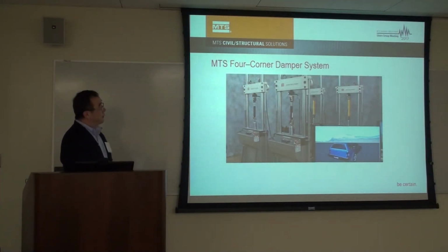So another trend we see is hybrid simulation being used in other industries like the auto industry. We have a car here, and the damper is a really nonlinear component, it is active, and it is coupled with the computer. So it's really tough to test those dampers. So we have a car modeled as a numerical substructure. The damper is tested in the lab, and this is a real-time hybrid simulation. This product is called the four-corner damper system.